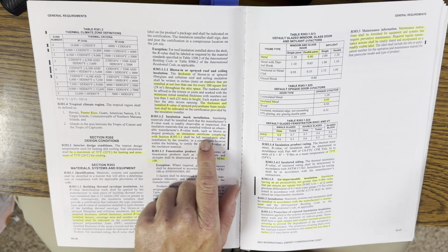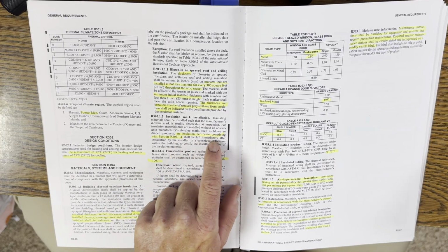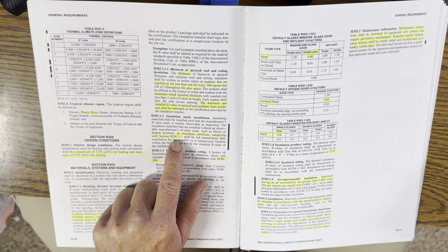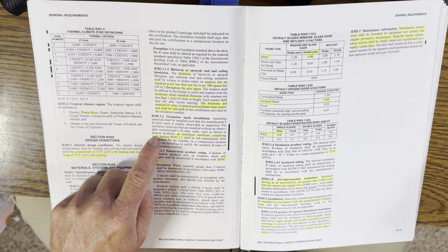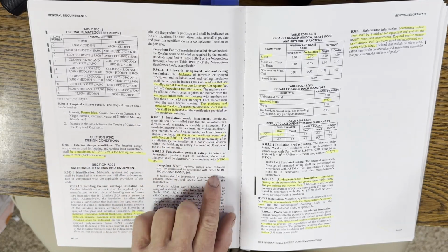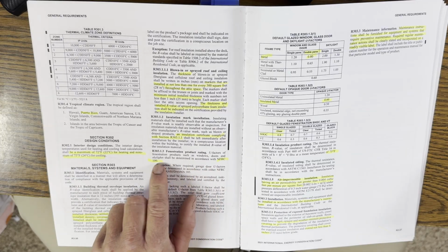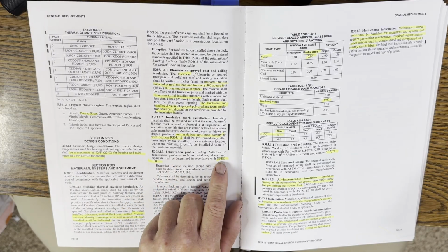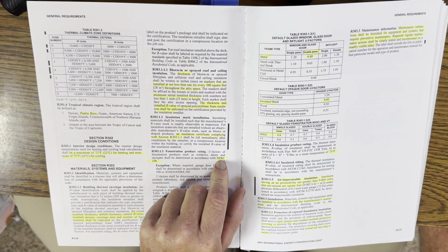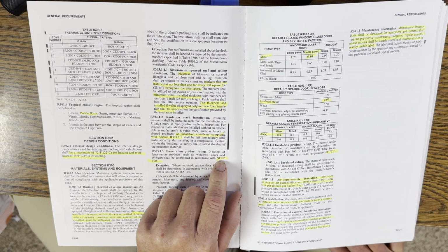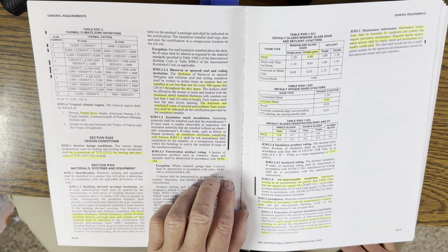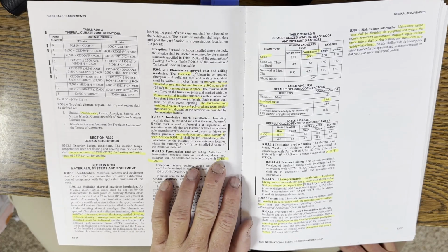An insulation certificate complying with section 303.1.1. I did have a question from this section here. Did have kind of a secondary question. It gave you a list of things. This was one of them. You needed to know NFRC, and I'm trying to think what it was. If the window is installed at a job site, how do you verify its U factor? Do you have to have it NFRC certified?